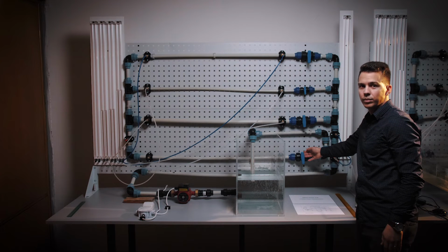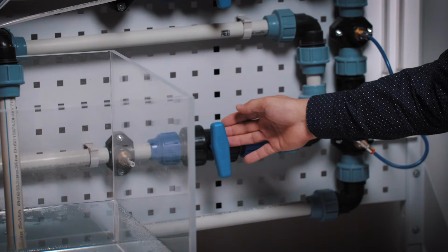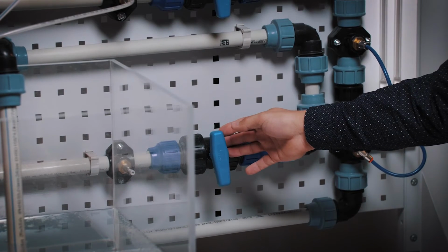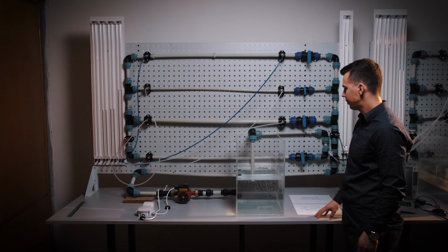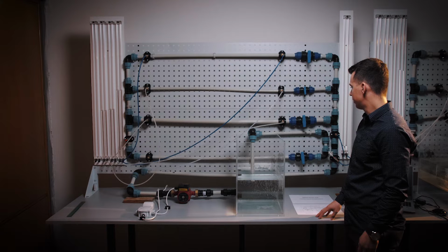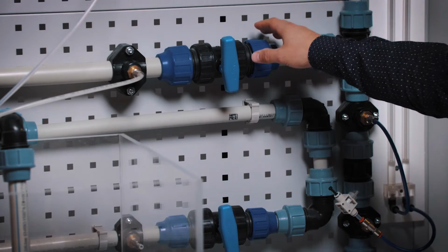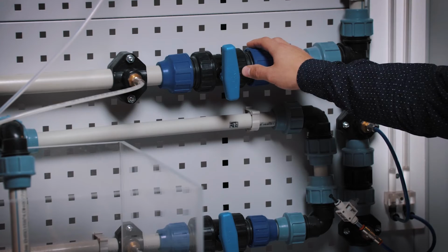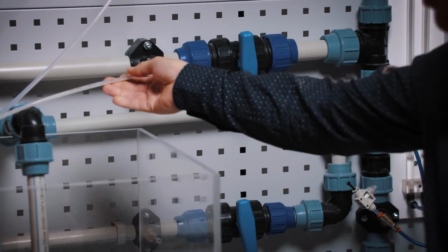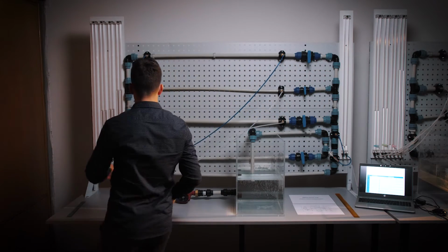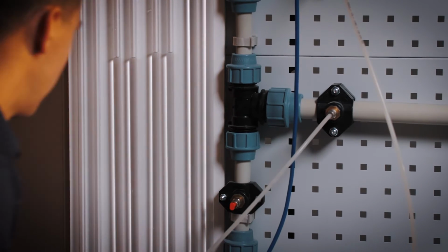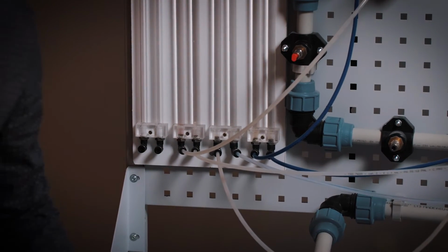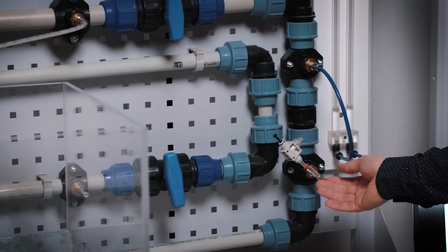Water flow is regulated by means of a ball valve of the waste branch of the circuit, which opens back into the tank. We will show the principle of measuring the pressure loss using the example of a pipe with an internal diameter of 23.2 millimeters. We will check the connection of the pressure taps to the piezometric tubes using hoses. We will also check the connection of the pressure taps on the orifice.